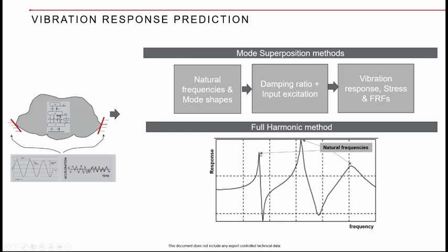So now with this, I summarized the basic background of what the important parameters or elements are that we have to focus on, like natural frequency for resonant conditions, damping for the response predictions, and the forcing function like random or harmonic or shock for predicting the responses against these excitation levels.